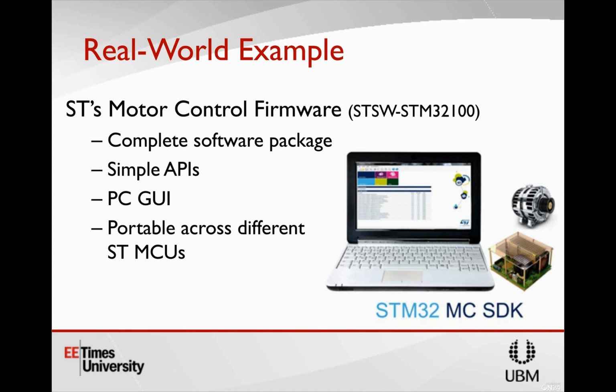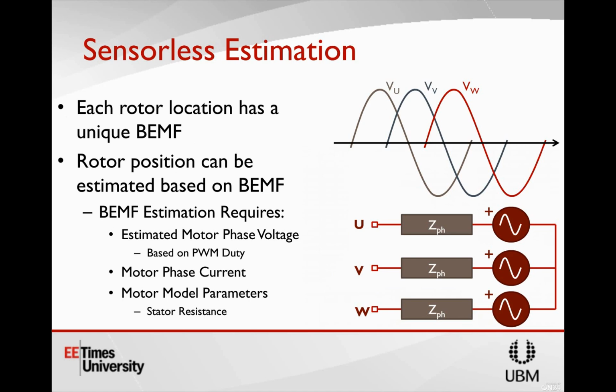The way that this is addressed is you'll bias your non-inverting difference amplifier that you're using to process that voltage drop across the sense resistor. And so you'll bias it to the midway point of your ADC, so you can measure both positive current and negative current.